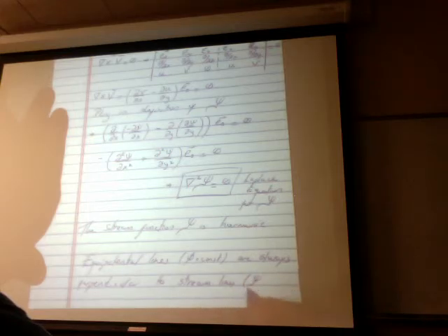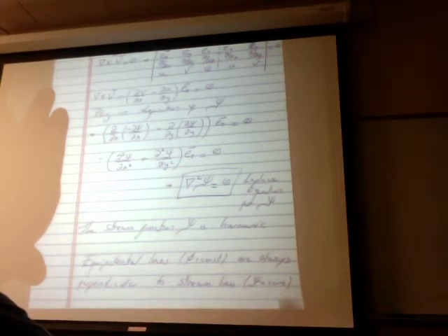So basically the potential function phi is what drives the flow. The equipotential lines are always perpendicular to the streamlines. The potential is equivalent to the pressure in this formulation. You have high potential, low potential, and the flow will just basically follow those lines.